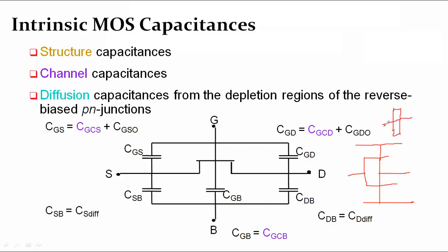These two we can call orthogonal, perpendicular to each other. If you use two layers, say layer 1 and layer 2, running parallel to each other, with this type of structure the capacitance will be more, like a parallel plate.